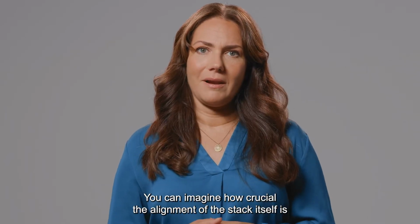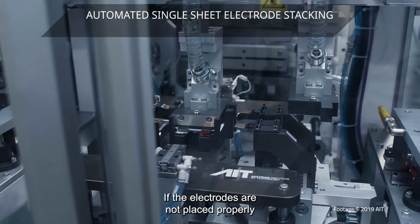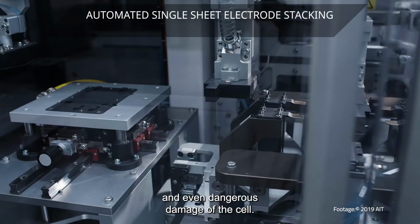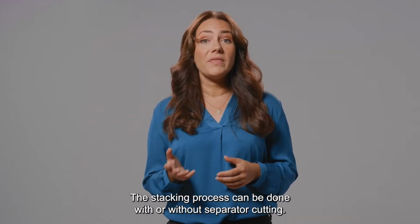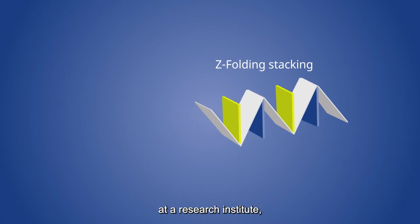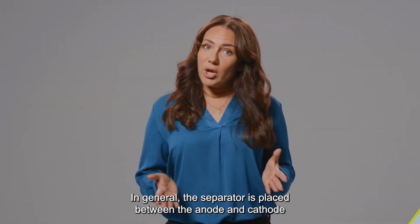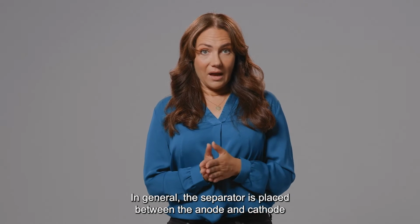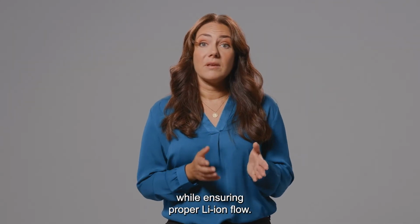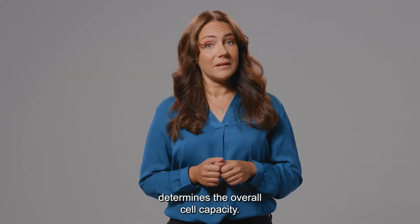You can imagine how crucial the alignment of the stack itself is. Some micrometers can make a difference. If the electrodes are not placed properly, it can lead to short circuit and even dangerous damage of the cell. The stacking process can be done with or without separator cutting. Conventional Z-folding is more commonly applied, but at a research institute, it can be more convenient using the single-sheet stacking approach. In general, the separator is placed between the anode and cathode to electronically insulate and avoid direct contact while ensuring proper lithium-ion flow. As already mentioned, the number of electrodes in the stack determines the overall cell capacity.